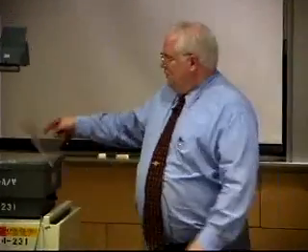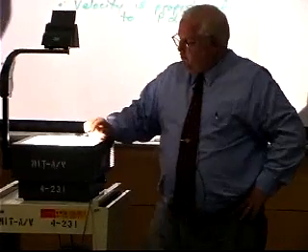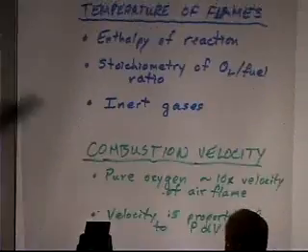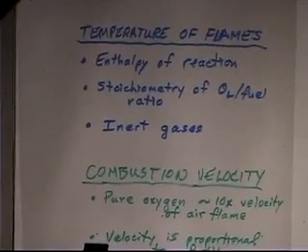So going back here, we're interested to estimate the temperature of a flame. We have to know the enthalpy of the reaction, the stoichiometric ratio. We also have to know how many inerts we have left over. There's a certain amount of heat given by this reaction.